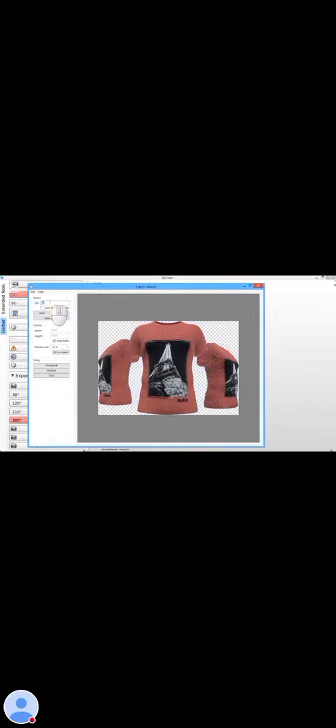So I'm going to say I want to do 300 dpi because we love large images. And I have the option to click Save Files Individually. What Save Files Individually will do is it will create an individual PNG for each one of my angles here. But once I click Save, I'll just go right here into my V12, and name this image test. Now it saved this image out and saved the individual files.